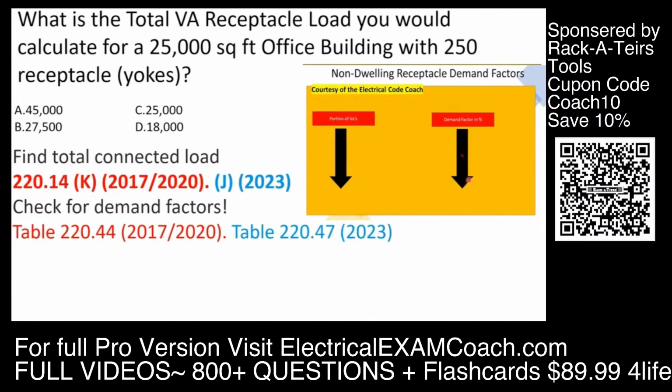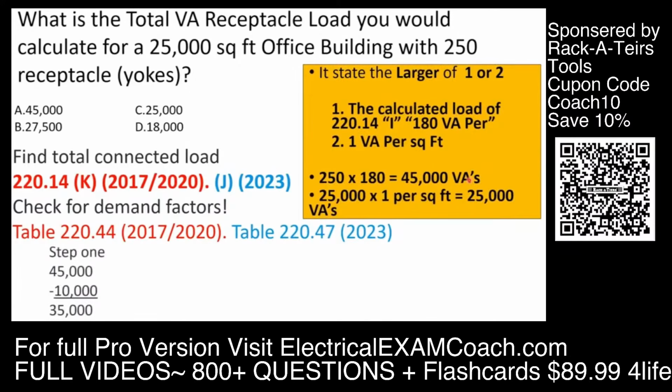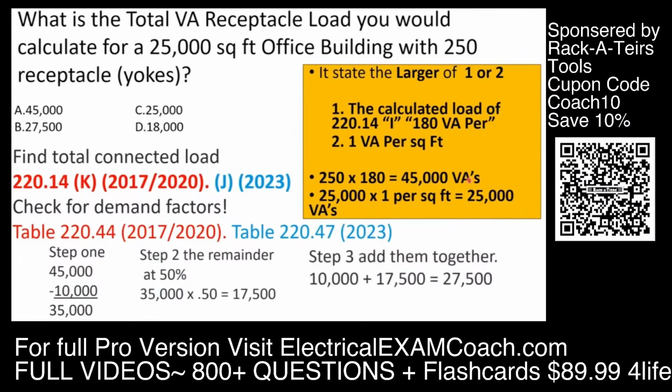And this table is for non-dwelling unit receptacles. Let me break it down one step at a time. What this table tells us to do is to take our first 10,000 VAs at 100%. Then we take that remainder and multiply it by 0.50. And then we can't forget to add the two back together.